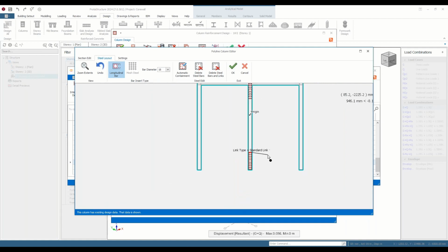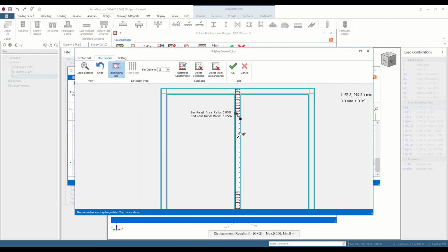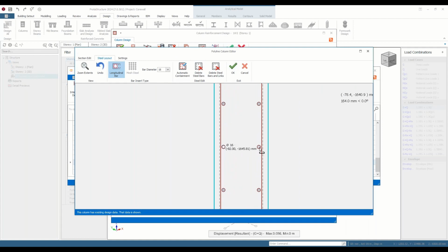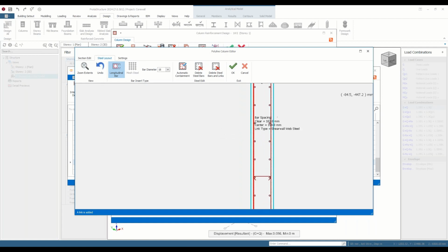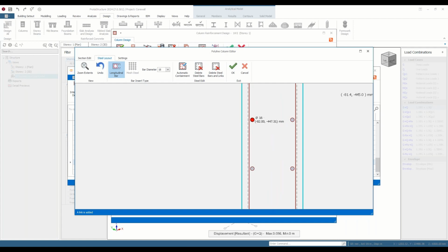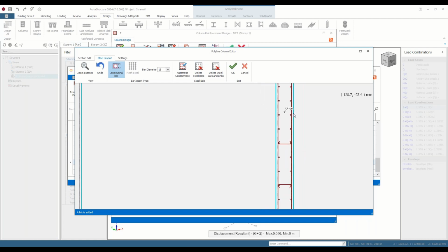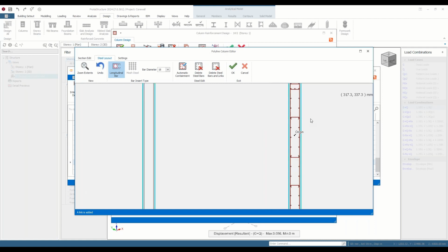You can also insert the web rebars. I'm using the same method as in columns. Now we can add our tie bars. To insert a tie bar, I'm just selecting the center of the rebar, and you can quickly create your tie bars just like this.